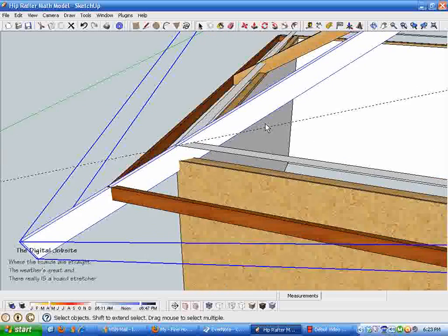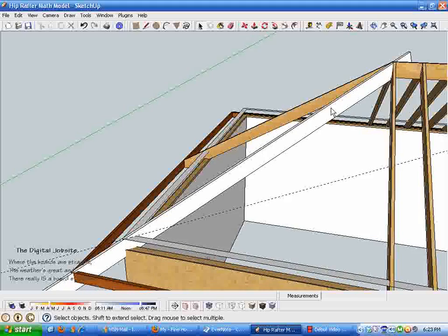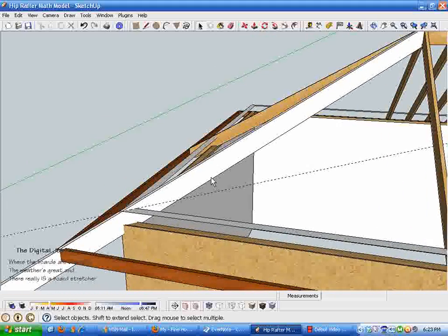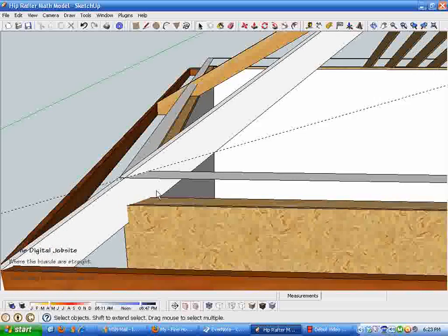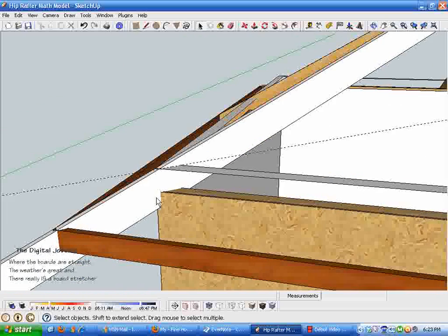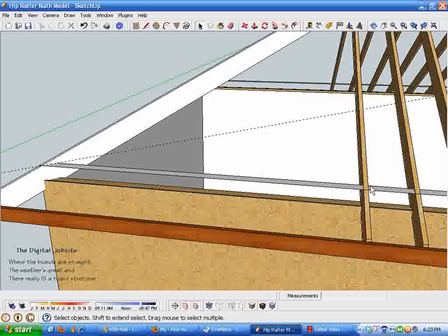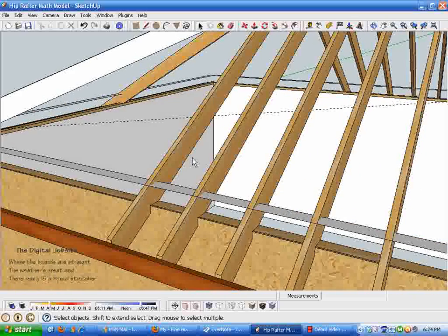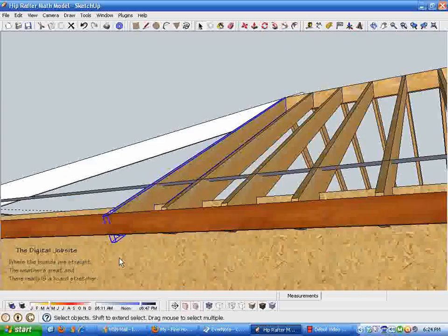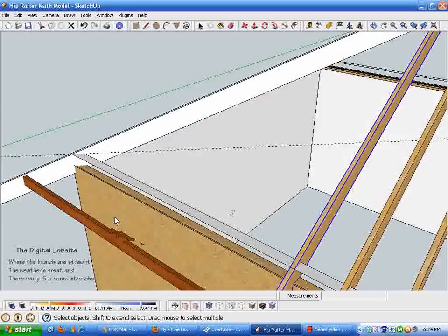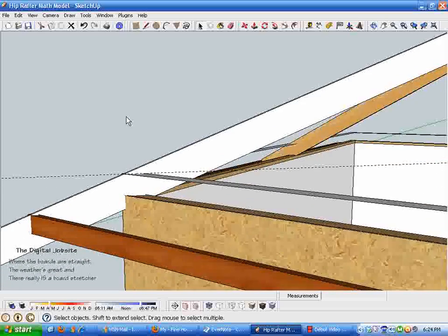So that's kind of the second step. First step is create the hinge. Second step, we created the board we're going to cut up for a hip rafter, put it exactly where we wanted it, pivoted it down, and now we're just going to draw the notches in it. Much like if you've seen my videos on regular rafter layout, that's how we created a common rafter, just by drawing lines and then notching it and cutting it for various intersections that it needs to take care of.